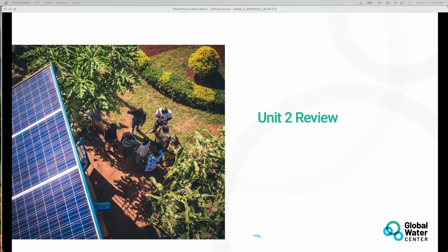For example, if we need to get more water, we put the screen casing on sandy formations, so that if it is sandy or a more porous formation, water can easily flow into the casing.